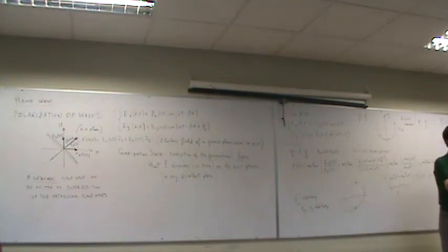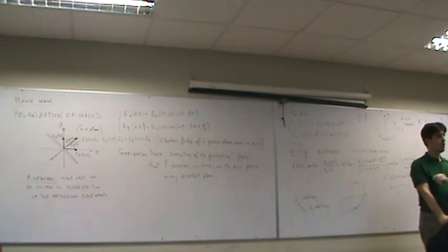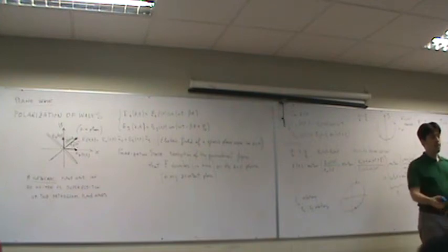Microwave link, it depends. Usually for terrestrial link, you take horizontal vertical polarization. For a simple reason. First, it is very simple to generate vertical horizontal polarization. And then, if you think about the effects of rain along the link,